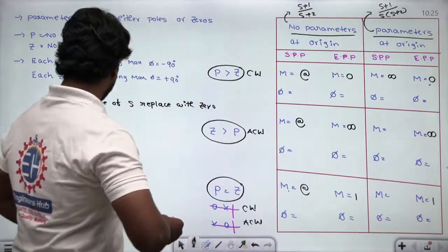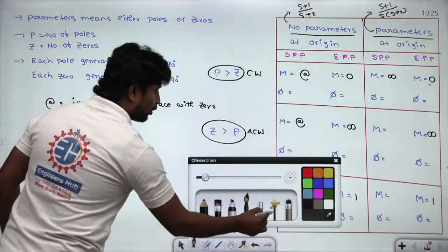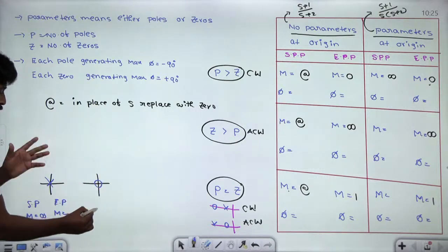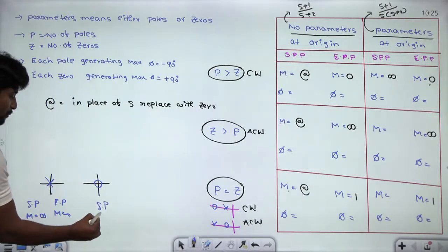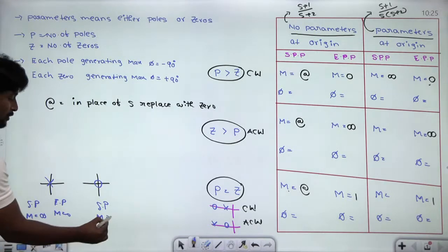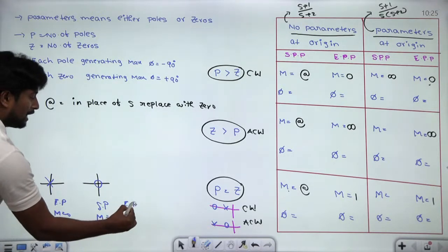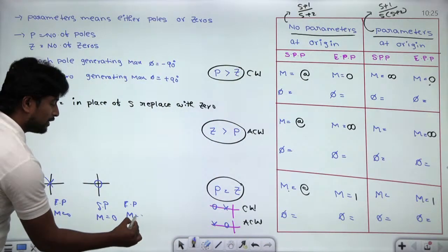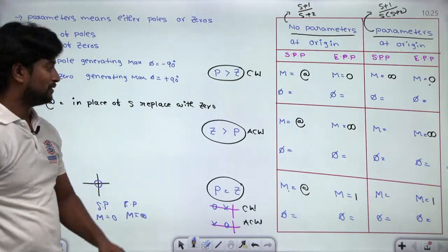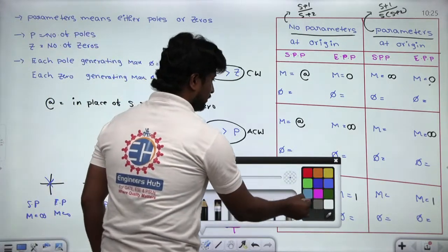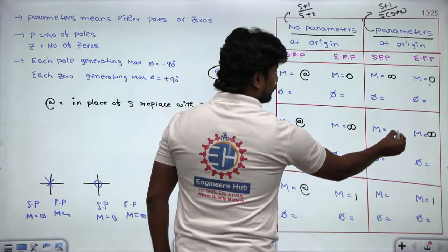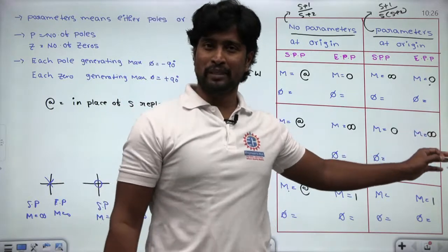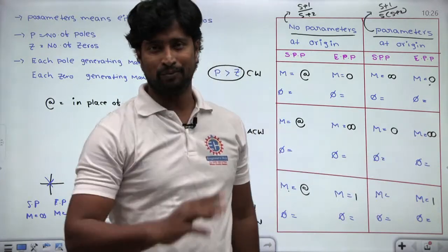Right? Next, even one zero at the origin, the opposite case. Starting point magnitude is the reverse: here it is 0, and the ending point magnitude, as you already know, is infinite. Infinite is the reverse, guys. So the plot comes from 0 and terminates at infinite.